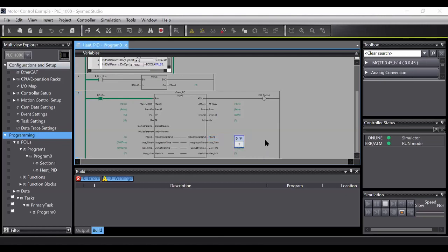You can double click on it, hit enter. Now retoggle your loop, change that off and on. Okay, now lower your set point to 5 or so, just so it wants to increase its output. Interesting.